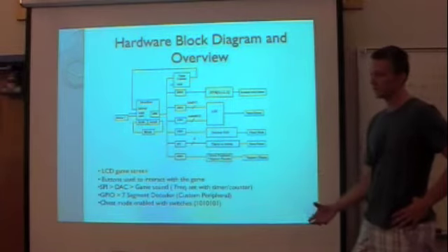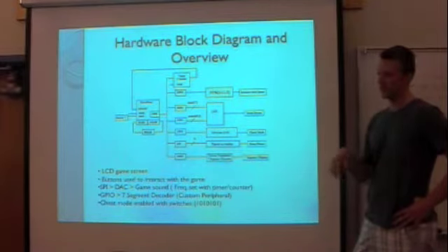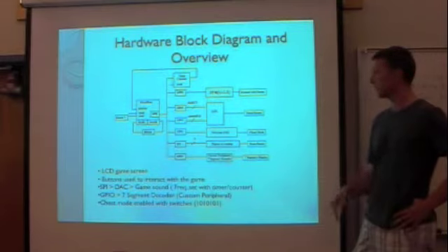We wrote the HDL and implemented that as the custom IP core. Since the 7 segments were right above the buttons, we used them to show the user what the buttons do. So we had the 7 segments say H, S, D for double down, right above the buttons that fit those functions. And the LCD is the game screen.